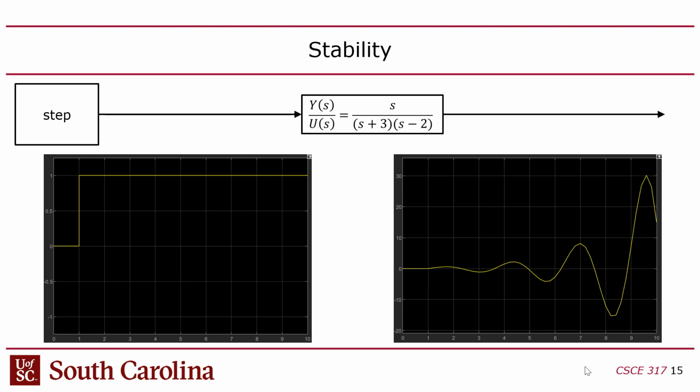So the step function, in this case, I had it step at 1 second, it goes from 0 to 1, and then it stays at 1. So just a square wave, and you put it in there, and you can see what MATLAB gives you. You get this kind of oscillating that builds and builds, and eventually continues to build up the amplitude. You see that?